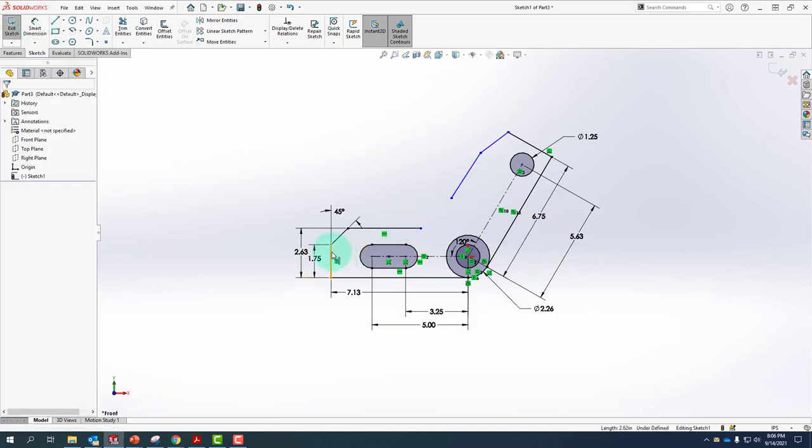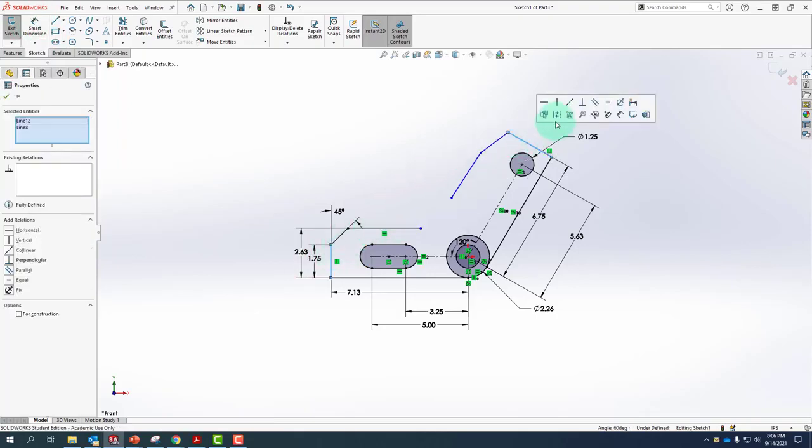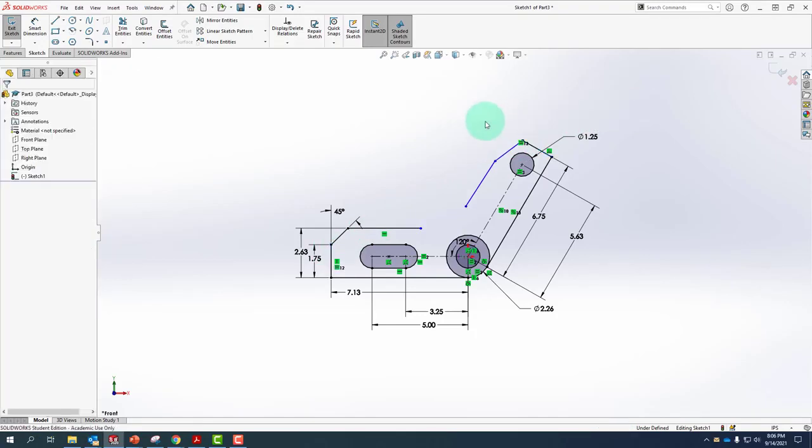For the 1.75, I'm going to select this line, hold down my control key and select that line and make those equal to each other. So what we're doing here is essentially capturing what's referred to as design intent when I have dimensions that I don't need to create again. And you say, well, but they're on the drawing. Well, they're on the drawing, but we don't need to add those to our part because assumedly we're going to make this solid model and have it made somehow in some advanced manufacturing process, not going to a machine shop where an individual machinist is going to make it.